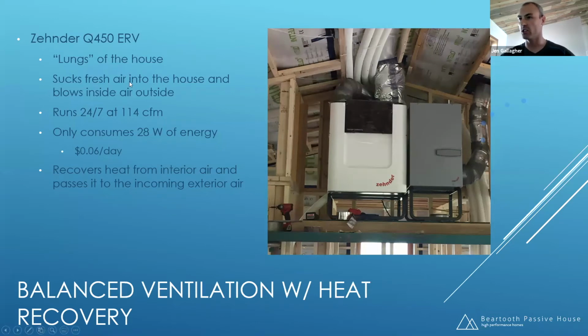So we need a ventilation system. So the Q450 is the lungs of our house. There are 2 fans in this white box. One fan sucks air into the house all of the time, and the other fan on this side is always blowing air out of the house, and they're balanced. They run 24/7, and our design rate is a little over 100 CFM. To give you a perspective, most bath fans that you will buy are usually at 80 or 110 CFM. So our continuous ventilation runs at about the same CFM rating as a larger bathroom fan.